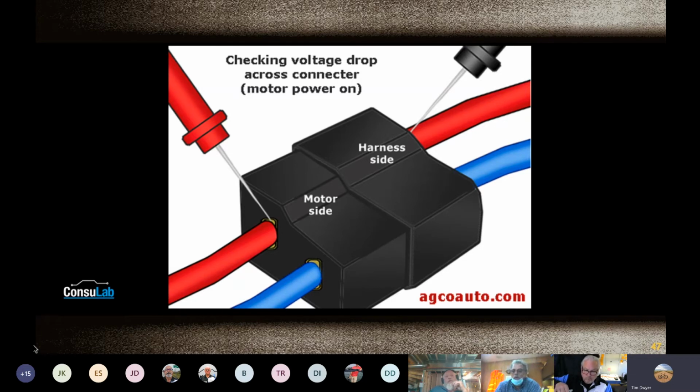Customer complaint, in this case, it's a motor. The motor isn't working. We're getting a 12-volt reading. That's a wire. We're a bird on a wire. Both our feet are on the red wire. There should be no reading on that meter, but we're getting a 12-volt reading. That tells me that inside that harness is an open, technically.